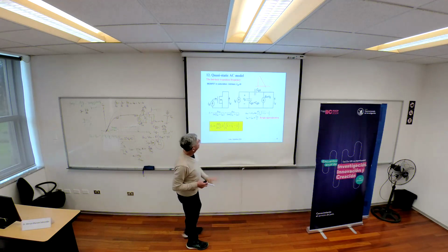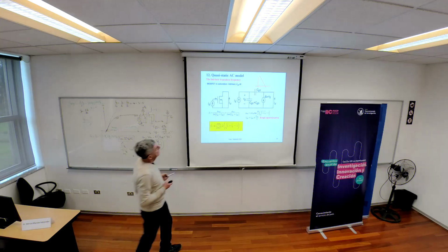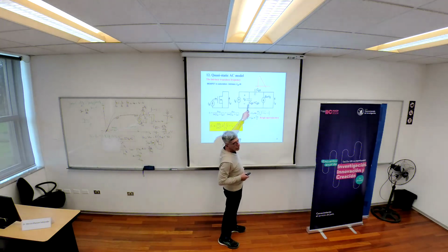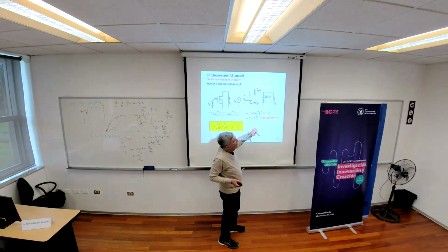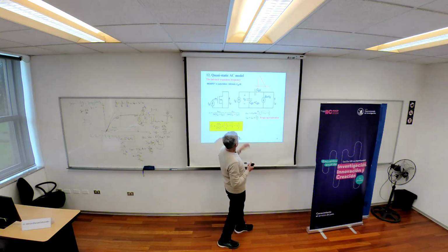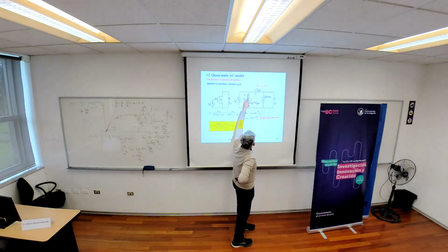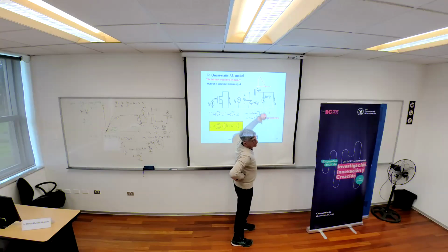Okay, approximately. In fact, we should take into account that CGD is in parallel with these two guys. Okay, not in parallel because it has an effect here. There is this current zone. But for the input impedance, it's in parallel with this. And part of the current here comes through this CGD.